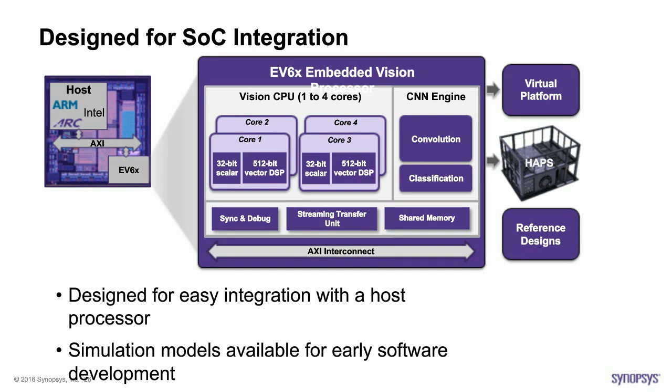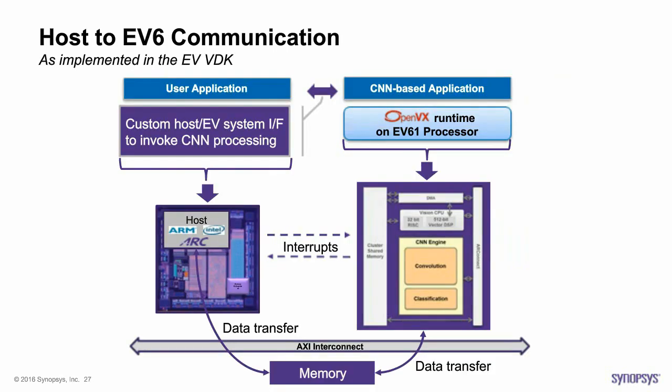The processor itself connects to an AXI bus, so that we have very good transfer rates from the frame buffer, but also so that there's very easy connection to the rest of the SoC to any host. Maybe there's another DSP in the system. We've seen that, or a GPU, as I mentioned.